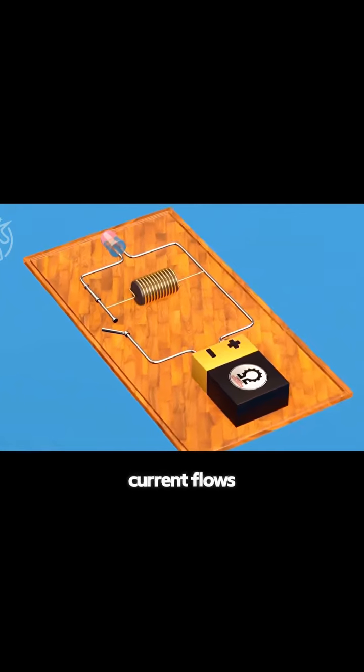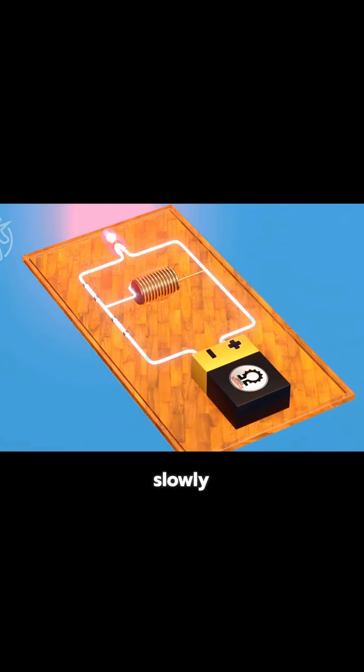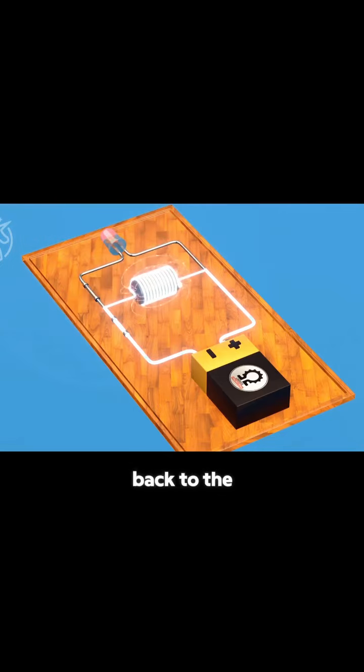When the switch closes, current flows toward both the inductor and the bulb. At first, the inductor's current increases slowly, because as the current starts flowing, it creates a magnetic field that opposes the change, acting like resistance. Once the current stabilizes, that resistance disappears, and since the inductor's path has less resistance than the bulb's, most current flows through the inductor back to the power source.